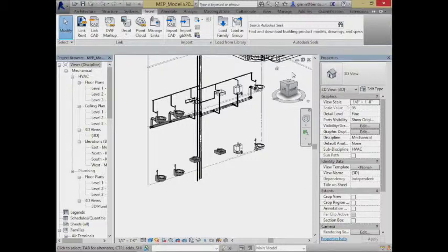Now, this guy over here had to have a little bit of slope to it. How about these guys up here? For the cold water line and the hot water line, do they need a slope? Nah, they don't actually need one. The reason is they can just run through the walls. They could run horizontally. They could even run uphill, if the water has back pressure on it, then it'll go up and down. You don't want an arbitrary number of bends. The more bends you put in, the more efficiency loss there is in the system, but it's less restrictive than trying to run the lateral lines.